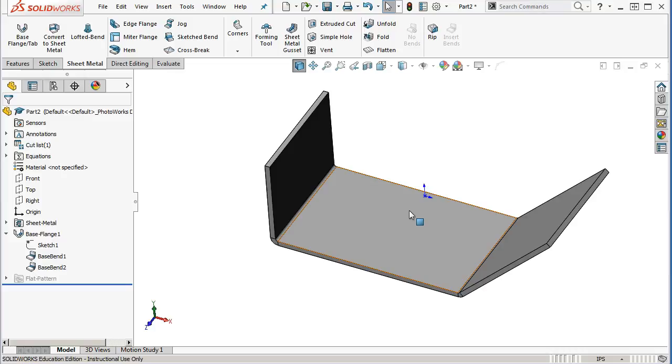You should be able to bend it within another 15 or 20 and stay within my plus or minus the 32nd. So on an inspection document, when it's bent up, yes, the finished dimensions are the critical dimensions, but realistically, if you come back and say, well, I bent everything at an inch when it was showing up at 7/8, and you didn't make the part, or the part didn't meet that final inspection, it wasn't a suggestion that you bend at that. You need to be pretty darn close to those bend references, or give me some feedback as the engineer and say, here's the variation, here's where the K factor came in, here's where the bend allowance comes, so that I can give you better numbers to set the stops, to set the brake where it needs to be to make those bends.